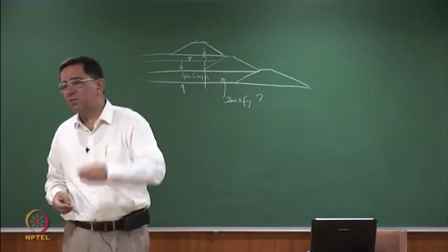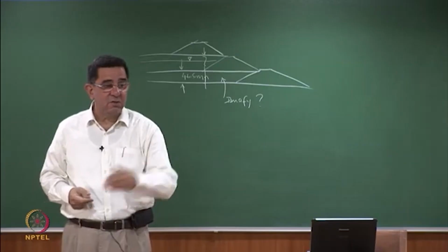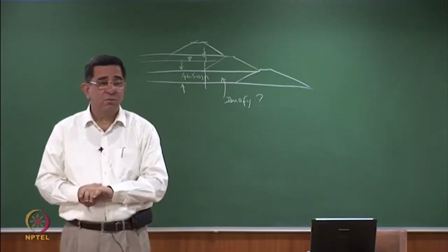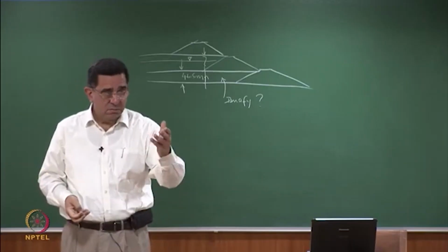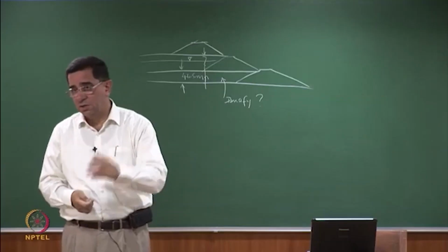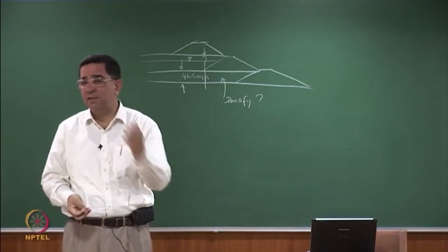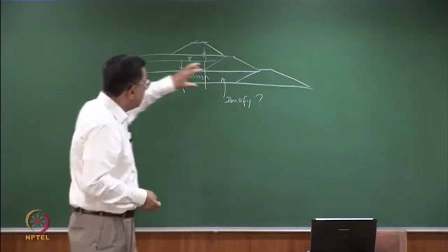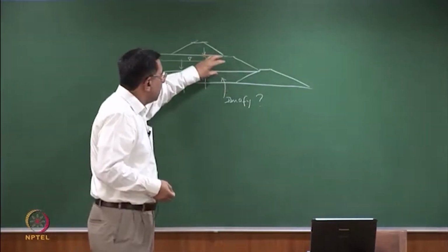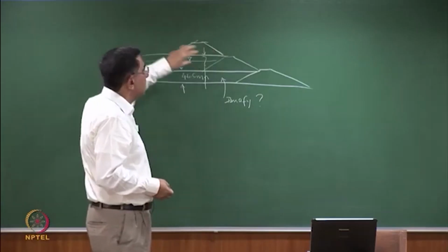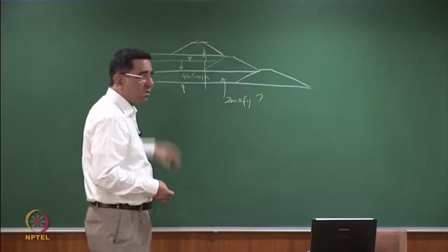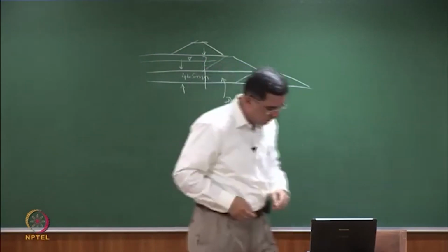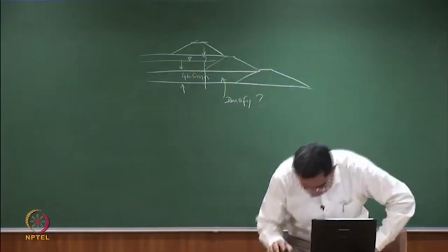Then you have to go for in situ densification as per all the other techniques which you may have done in underground improvement, like all those vibroflotation, dynamic compaction. They are very expensive techniques, so they are rarely adopted. So in the upstream method, the staged embankments or the incrementally raised embankments are resting on soft soil, loose soil, which is hydraulically deposited.